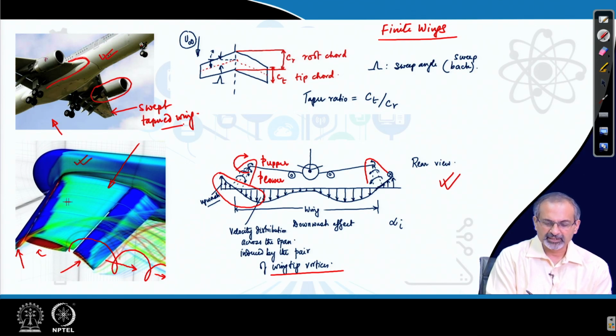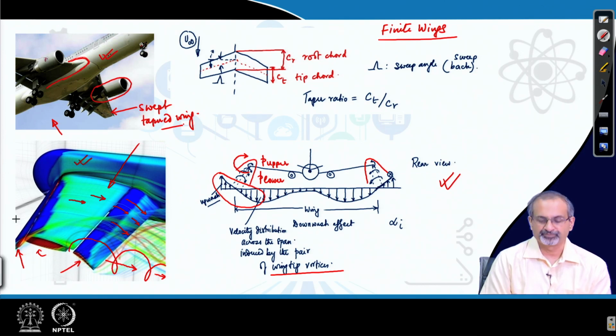And here additionally you can figure out that apart from the wing tip region, the flow tends to behave smoothly, it is not detached, it remains attached all the way through to the flaps, and therefore, the high lift devices are nicely getting the flow to move over that large camber that is created, and an augmented surface area that is created, which generates more lift.